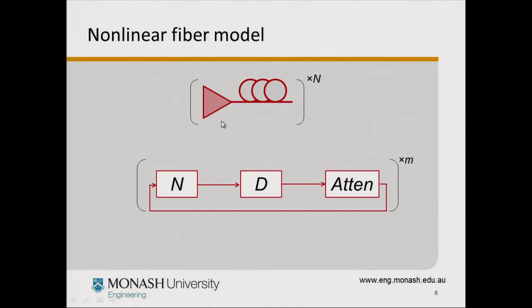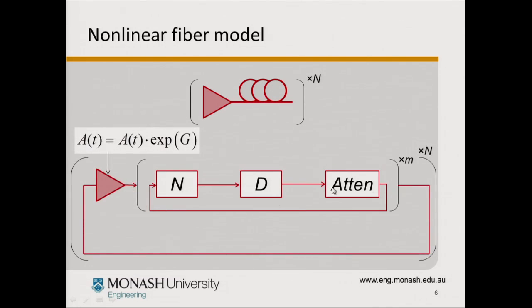Now, in an optical link, of course, they are often thousands of kilometers, as Cedric has already mentioned. You clearly cannot go there with no amplifiers. So we have these things called optical amplifiers in the link, and you can add these to the model. Every few steps, when the attenuation is such that the signal needs amplification, we can model an amplifier, and then we go into the next span and start the process again. So you have two nested for loops in your nonlinear modeling.